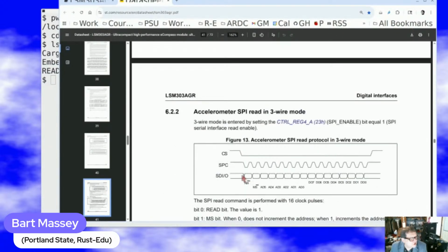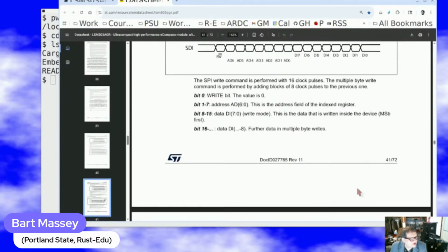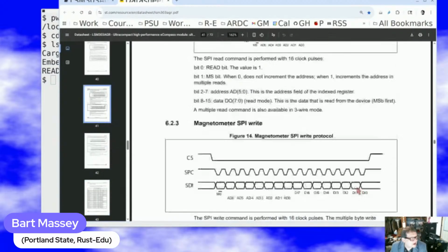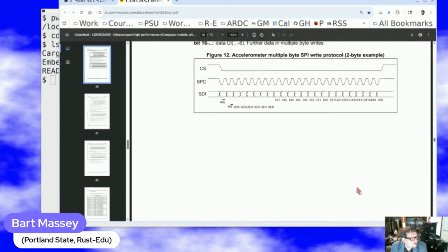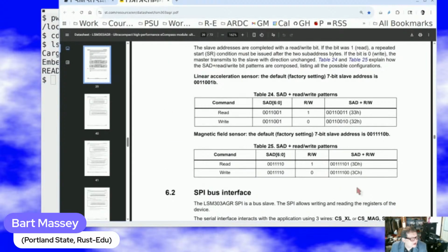And so a normal write to the accelerometer writes the register address of the register you want to mess with, and then writes the data that goes in that register. And similarly, a read, there's SPI, we don't care. I don't know what happened to I squared C here. Here's I squared, this is SPI, I don't care.